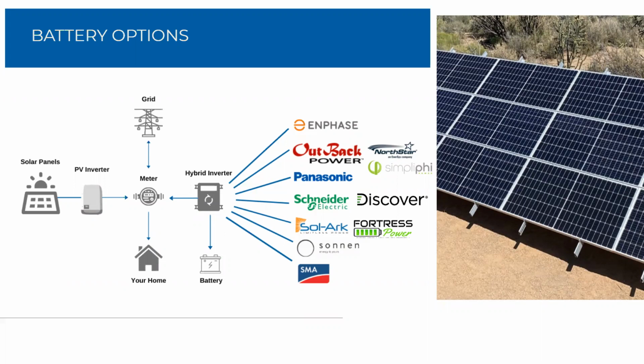So if you sit down with your homeowner and you say, when the grid goes down you understand that you're running on battery power only, if you have, let's just say, a few kitchen outlets, you have to tell the homeowner, you cannot run your blender and your microwave and your toaster oven at the same time. So you don't necessarily have to size your inverter to run 3 1,000-watt appliances simultaneously. Because realistically, if it's either the blender or the microwave or the toaster oven, then you only are going to be experiencing 1,000 watts running at a given time.